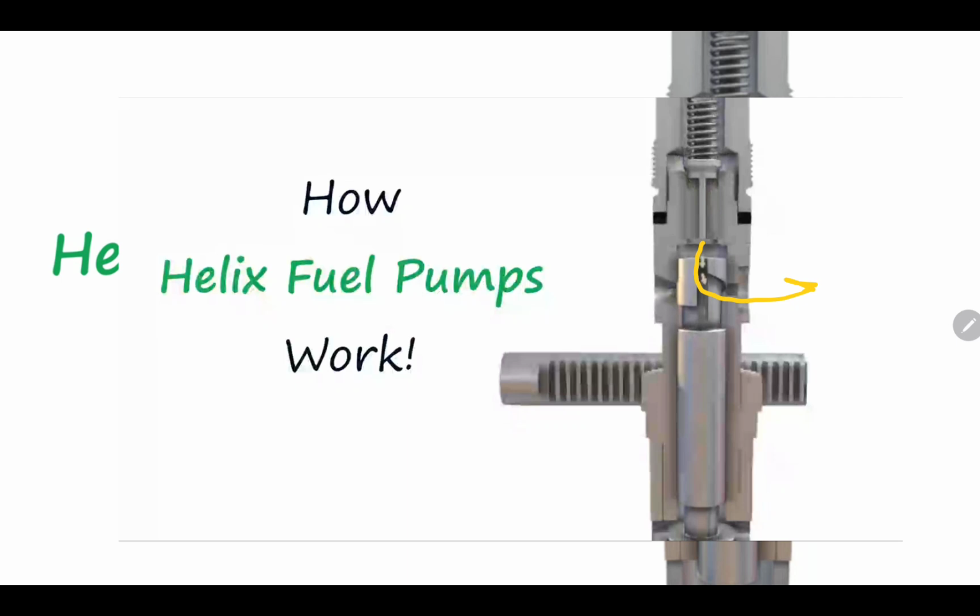So, does the inline pump and the plunger and barrel assembly require 2 ports, inlet and return? No, it can operate with a single port. Okay? So, according to the design, some pumps may have 2 ports, one for the inlet and one for return, and some pumps might have only 1 port for both inlet of fuel and return.